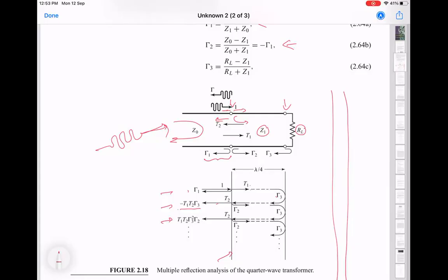In practice, all of this will happen in no time, because you cannot distinguish between 0.01 versus 0.000001 in terms of gamma. If you're trying to really look at how gamma changes as a function of time, you just have to look at the return power. You can measure it. You go very quickly to a small enough value that you won't be able to distinguish. But that's how you connect these two points, that the impedance matching is only at one frequency.